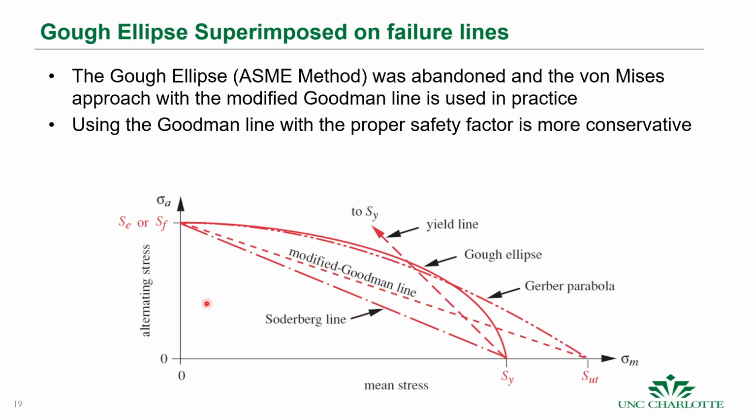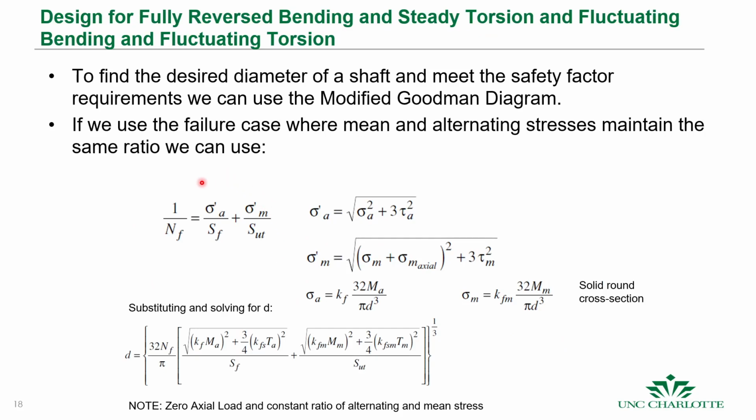You get your alternating stress and your mean stress here, and we use that definition of the safety factor to introduce our expressions for our loads, which included the diameter, so we could back out the diameter. It automatically included the fatigue strength and loading conditions for both alternating and mean loads for the bending stresses due to the transverse stresses and the applied torques to that shaft.